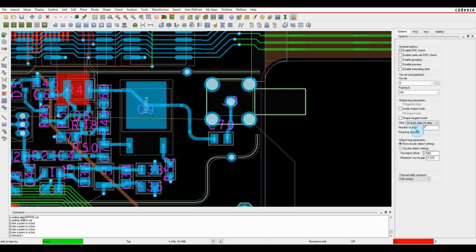I can then choose I want it on both sides of the track, and then I specify a couple of default values. So maybe I want 1 millimeter from the clearance of the vias. When I click the object now, I get a preview of what's going to happen, but because it's a preview, I can actually make adjustments.